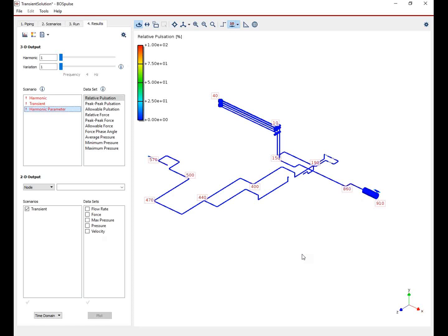When working with a piping system or designing a new piping system, when do you typically need to perform a pulsation analysis? Well, the opinions about this one really change. We believe that the API 618 for compressors gives you some guidelines regarding this. It's always good to do a pre-study, so look at your compressor together with your pulsation bottle, to look at the effectiveness of this pulsation bottle to dampen the pulsations of your specific compressor. You can do this relatively soon in your design. You only need to know the compressor and the pulsation bottle, and not the exact piping.